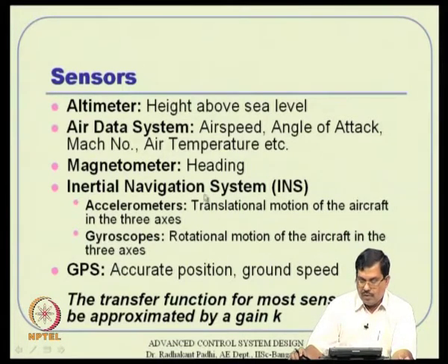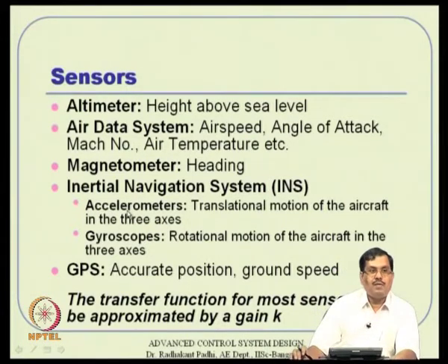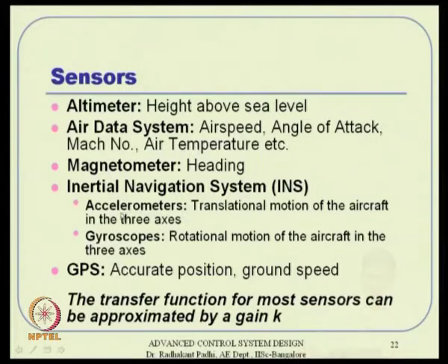So if your initial information is really good, then it does not lead to too many accuracy issues. They have their own sensing units, their own filters in the loop, and it is a complex unit essentially, and nevertheless it does not require any additional external support. Depending on the level of sophistication, it can give you very good information. But as the duration goes up, they have this problem of drifting, they have a constant bias acting, and integration of that leads to large error. So, many issues are there.